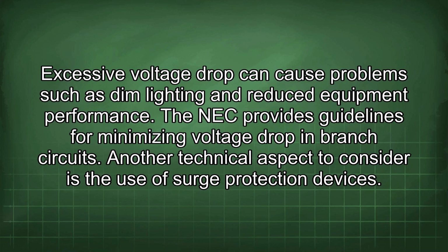Excessive voltage drop can cause problems such as dim lighting and reduced equipment performance. The NEC provides guidelines for minimizing voltage drop in branch circuits. Another technical aspect to consider is the use of surge protection devices.